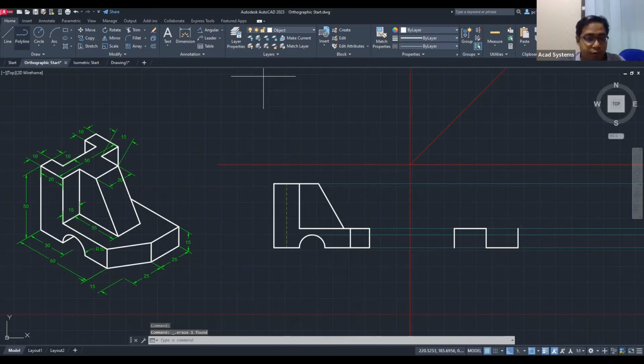Right, so front view over here, and then we also have this straight up over here. So from here, we can just start drawing from the left, and it will have the distance of 15. So I'm going to create a line with 15 and straight up perpendicularly. And this should have the distance of 20. So let me just input 20 over here and just snap perpendicularly downwards.